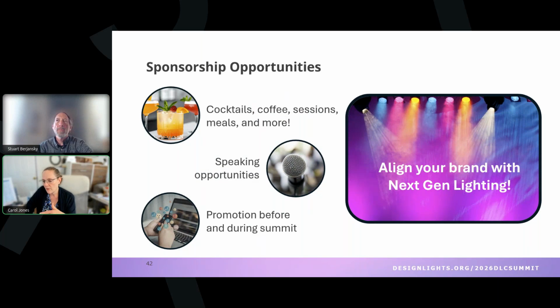So DALI 2 with a wired system is one way of using DALI, and D4i with a wireless layer is another way. DALI Plus is DALI equipment with its own wireless. So for anything that is using DALI 2 wired, D4i, DALI Plus, any of those, they are all DALI. They all can communicate with each other. They're all backwards compatible in terms of the data and how that's all put together. So I hope that answers your question in terms of which one do you use. It depends on the system and the project.